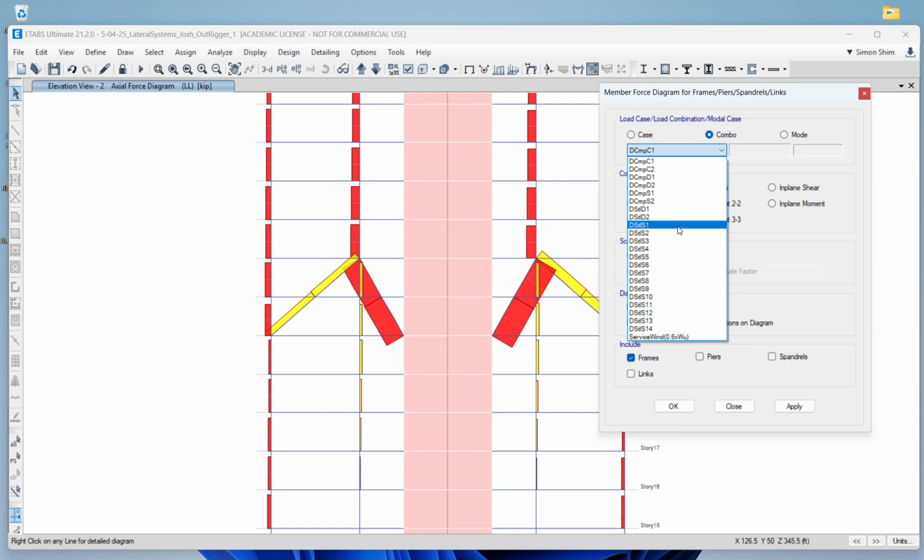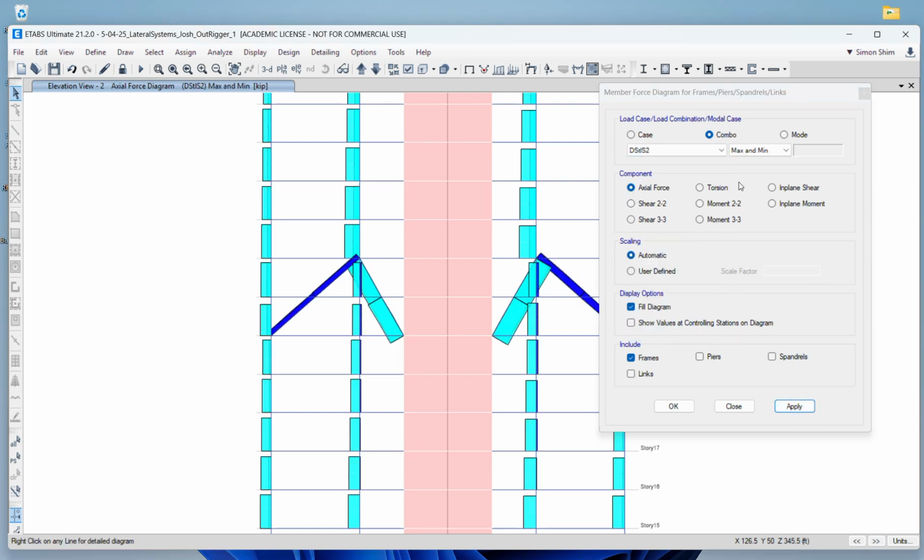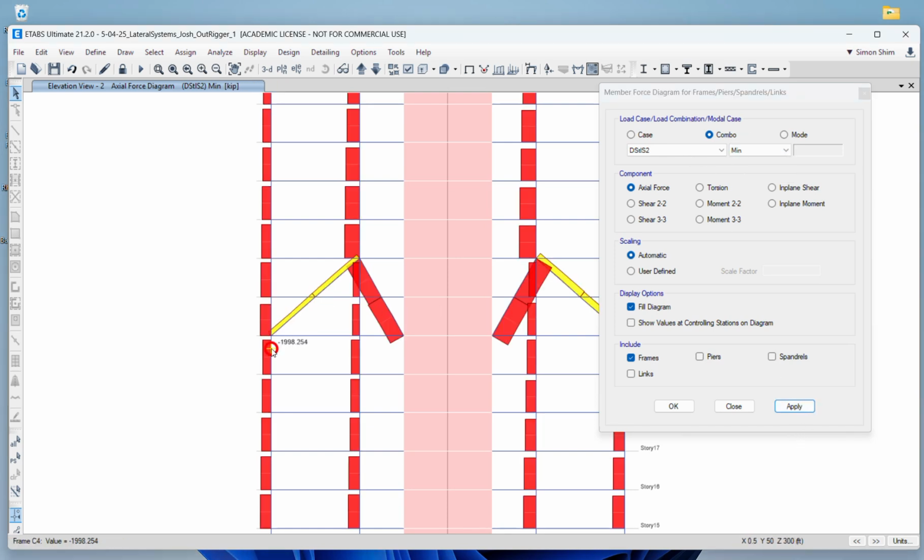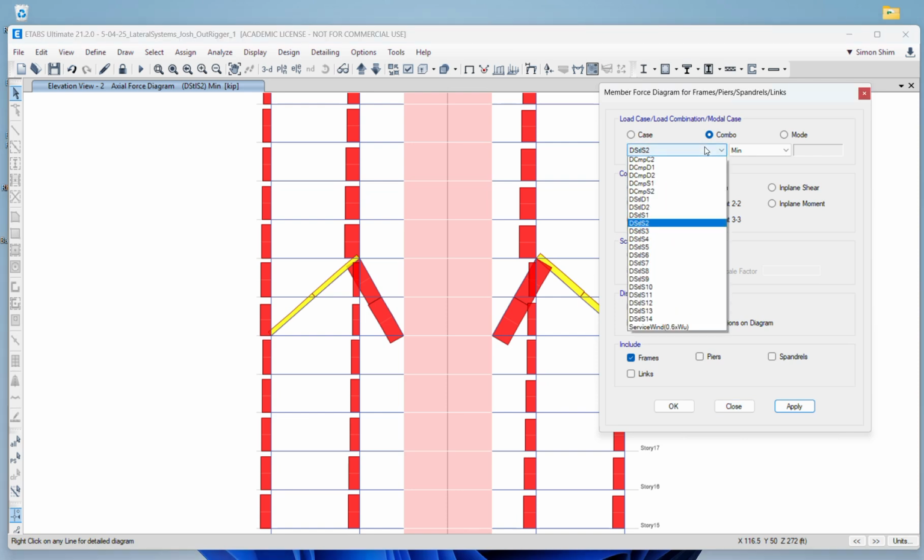when you look at this, ETABS gives you both negative and maximum. I think in this case anyway, this negative is governing. But we still have some situations there. We need to carefully review it. So obviously the column below is governed also by gravity and lateral effect.